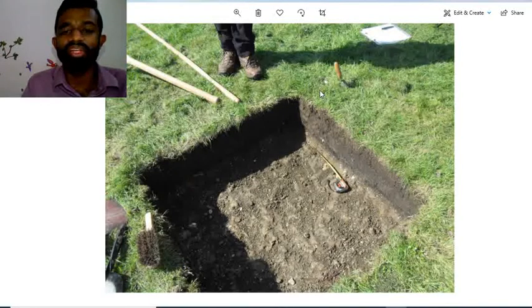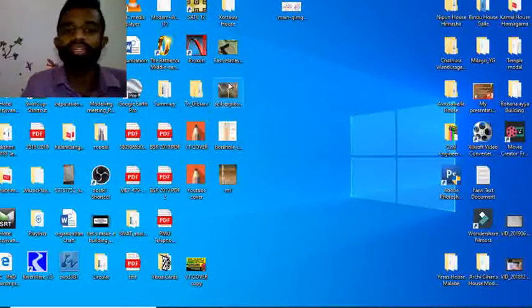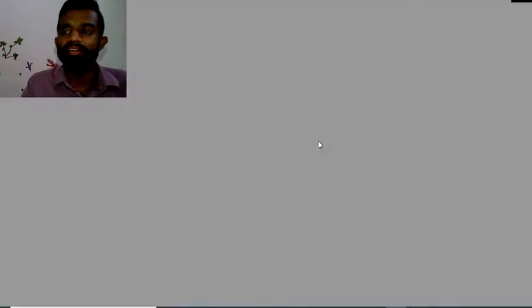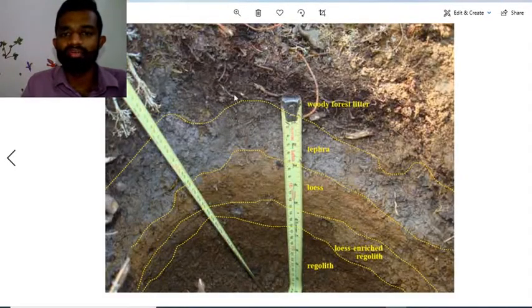soil. So if the soil is weak, it will badly affect your construction or house design. The house can be cracked. Sometimes the house can be tilted in one direction if there are different types of soils in your land, and it may lead to differential settlements. That will lead to cracks and leaning buildings. Sometimes buildings can be destroyed, and accidents can happen. So it's very necessary.